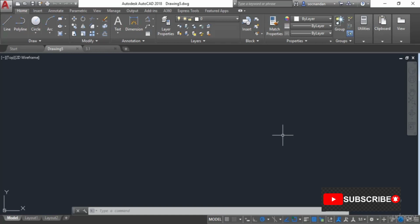In this video, I will tell you about the point and revision cloud tools of AutoCAD. So I'll start with the point tool, and in order to make a point in AutoCAD, you need to use its command equivalent, which is PO or point. So let's type PO on command line and press enter. Now click at a point, and here we have it, the point is made.